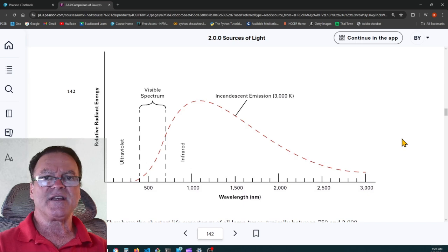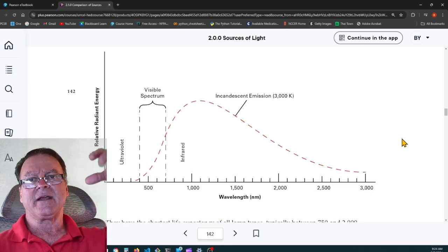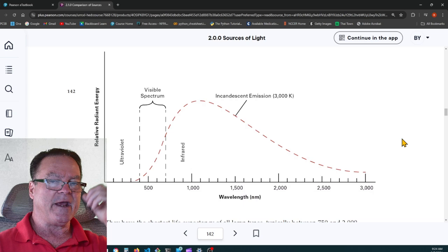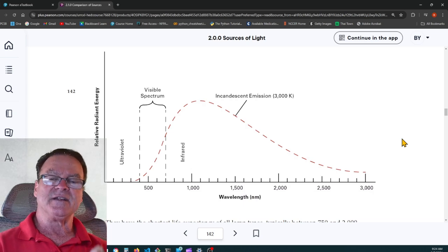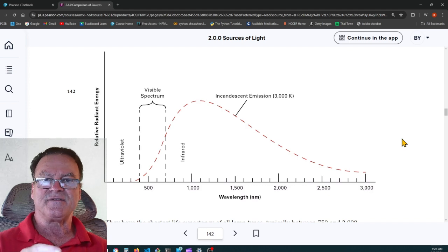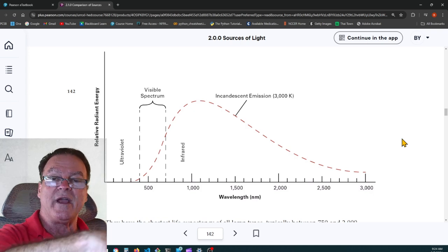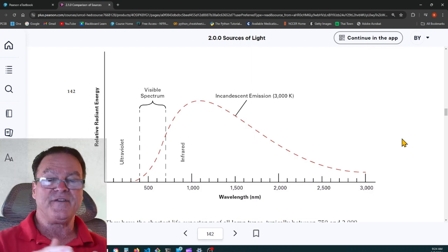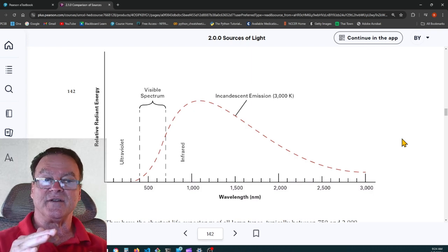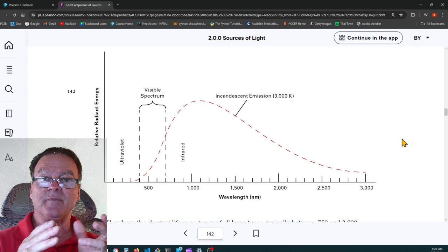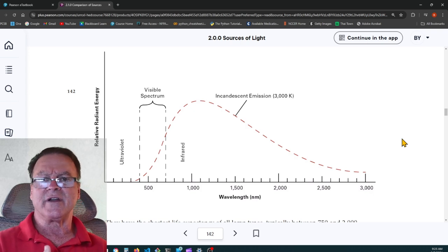There are some recessed fixtures that go up in your attic, and they will say, IC, insulation contact. The insulation can touch that recessed fixture. Others will say non-IC, non-insulation contact, meaning you have to dig the insulation 3 inches away from the light. If the insulation falls against the light, the can that the lamp is in, that light will overheat.